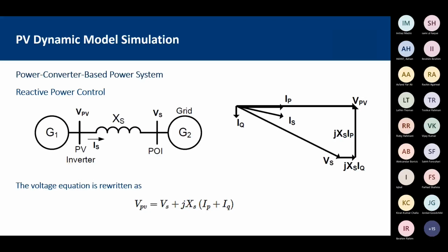Inverters are smart devices, so we can run those algorithms or controls which can control the reactive current injection and control the voltage accordingly. And that's where they become grid firming or grid forming inverters.